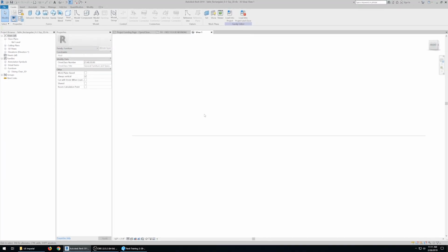What might be a little shocking is when you open that particular one, you're like, what the heck is going on? I see a line, and where the heck am I? Well, by default, these open in a 3D view, and this is a unique 2D family that we created for construction documents. So you need to go to the plan view or the view that you want to edit, because some of the 2D families that we have might actually have different views. We make them like the old smart CAD blocks where you can see this elevation, you can see this elevation, and you can see the plan. But when you go to 3D, it looks like the old SketchUp tree, and I'll show you that here momentarily with the toilet.